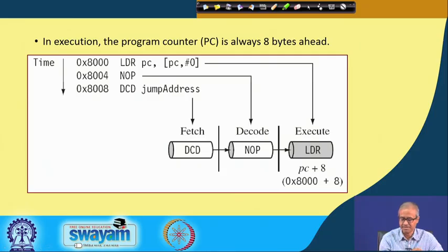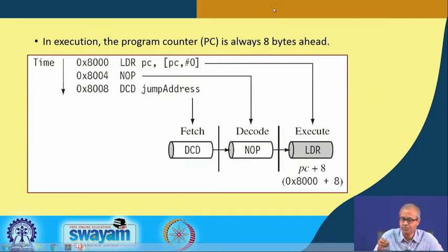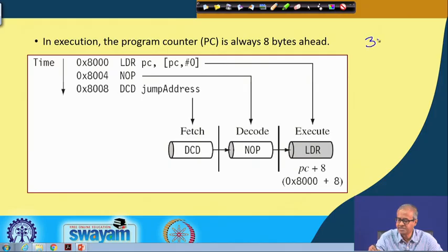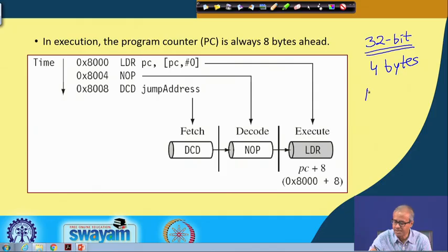So, all of these prevent the pipeline from operating at the maximum clock frequency. Just another thing, let me tell you, in this ARM7 kind of architecture, a 3-stage pipeline, when an instruction reaches the execute phase. Now, one thing you remember, I told you all instructions are 32-bit instructions. This we shall see later also in some detail. 32-bit instruction means 4 bytes, and the memory that you have is byte addressable.